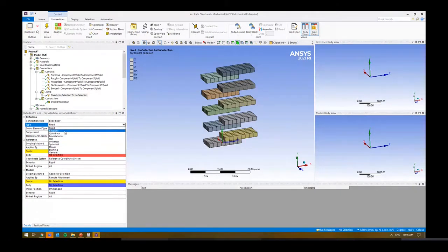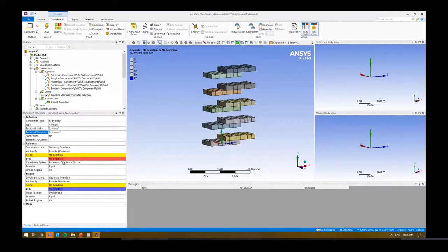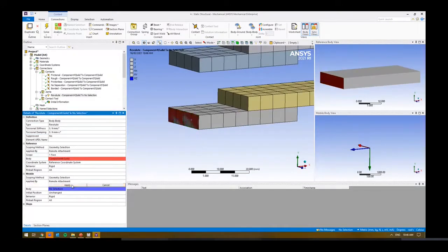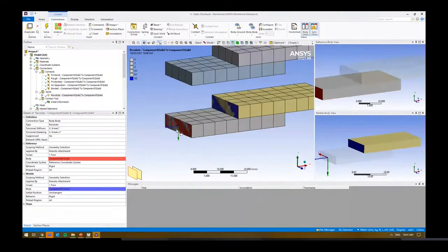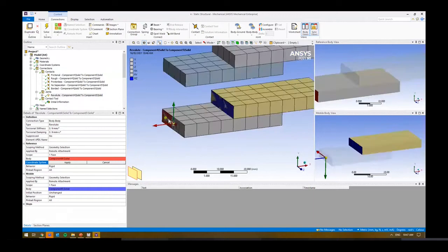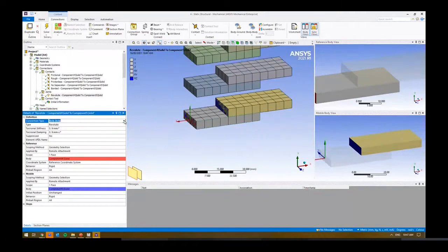So you can see here the type, we've got different conditions as well. If you select a revolute joint, we've got options for stiffness and dampening. And generally what you want to do is specify a component here, and let's just say between that as well. And based on the RZ, it will start to revolve around that specific area, right? In this particular case, we probably want to go in and make some changes to the actual coordinate system, because we want it to revolve, say, around the Z coordinate system, right? So the one in blue. And we can start to make some changes around there, right?